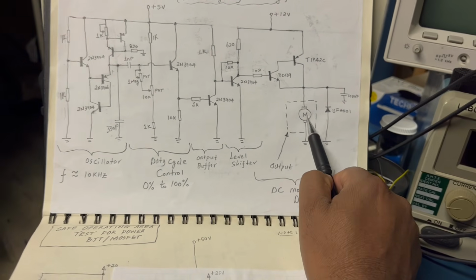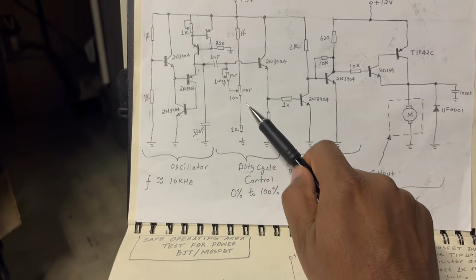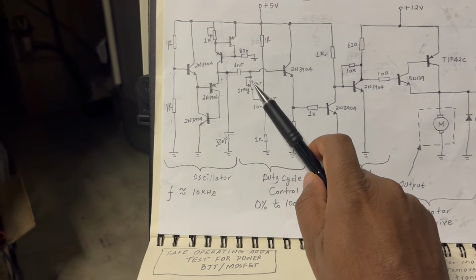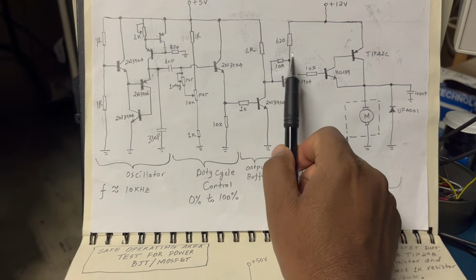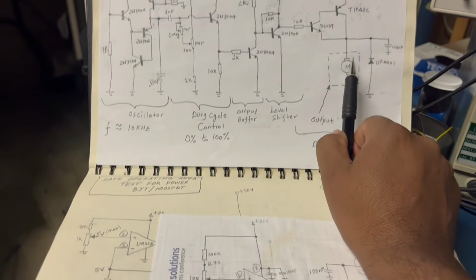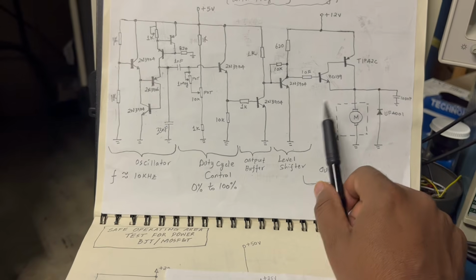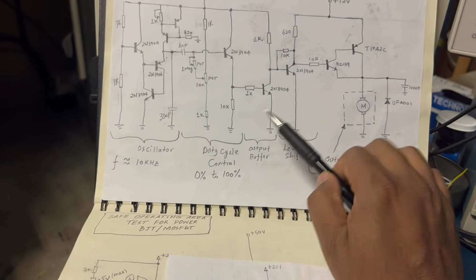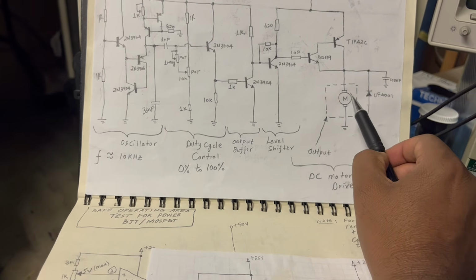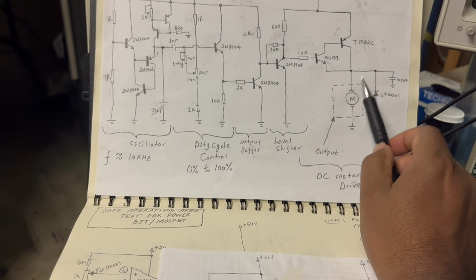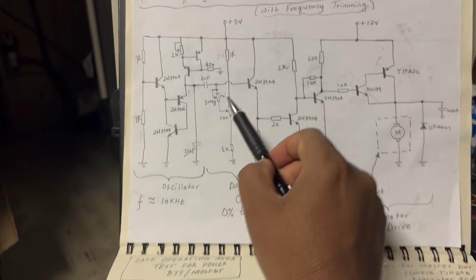Or as the frequency goes down, the average voltage will go down as well. Now that gets inverted and will generate a higher DC offset in here, and that higher DC offset will generate a higher duty cycle, thereby maintaining a specific speed in this motor. That's one application you can use. There are a lot of other applications in a closed loop environment, as long as you can generate a proportional voltage that varies with the quantity that you're controlling. You can feed it back into here.